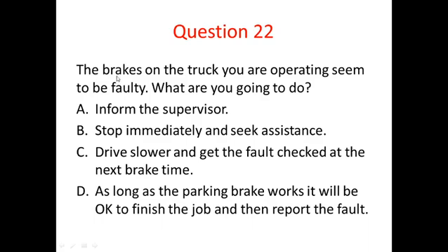22. The brakes on the truck you are operating seem to be faulty. What are you going to do about it? Well, the safest thing to do would be to stop immediately, and then obviously make sure you get that looked at. Seek assistance. If the truck needs to be left for you to seek assistance, then you'd want to make sure that no one else uses that truck via a vehicle off-road label. Also make sure you remove the keys as well when doing that.